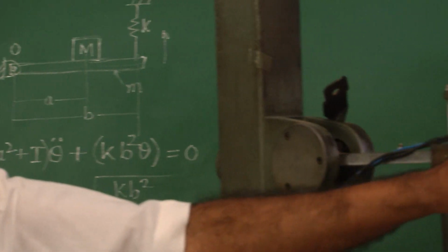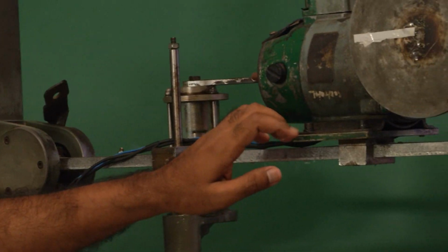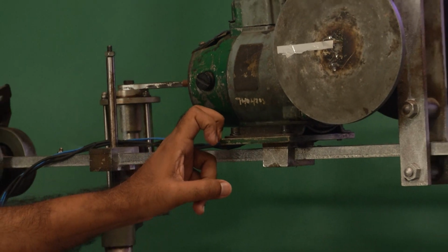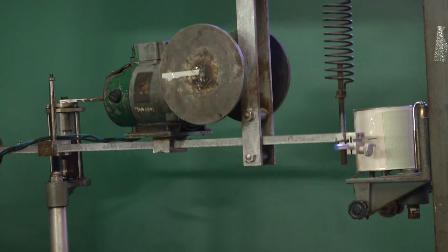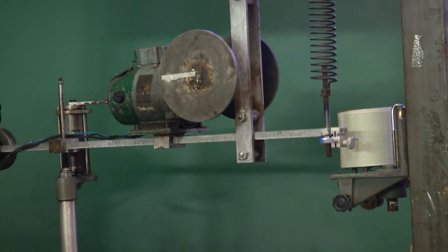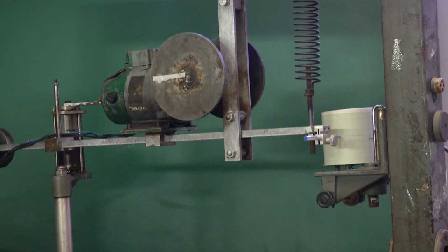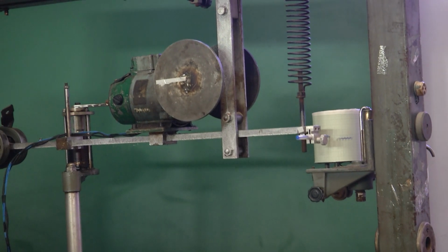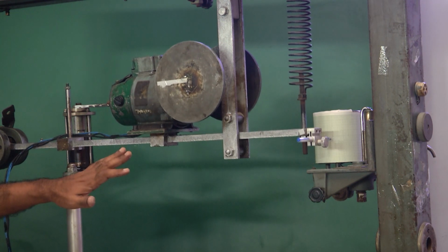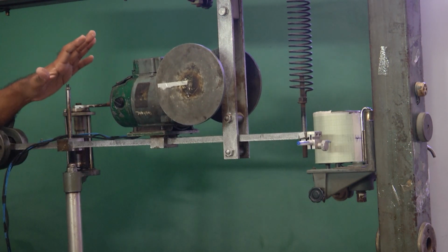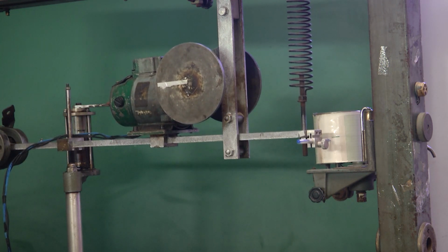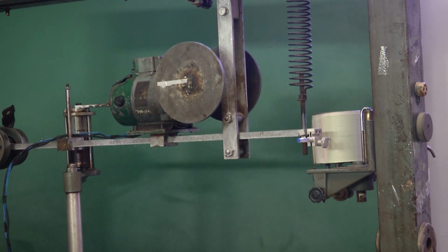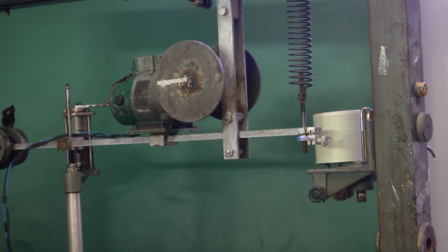Experimentally, how do I find the natural frequency? Now, you can see that if I perturb it, just like we discussed in the first topic, I give an initial displacement and then release it. So, x naught is given some value, and v naught, the initial velocity, is 0 at time t equal to 0. Once we give that initial disturbance and release it, the whole system vibrates naturally at its period of oscillation. So, the free vibration natural frequency is what we observe here.